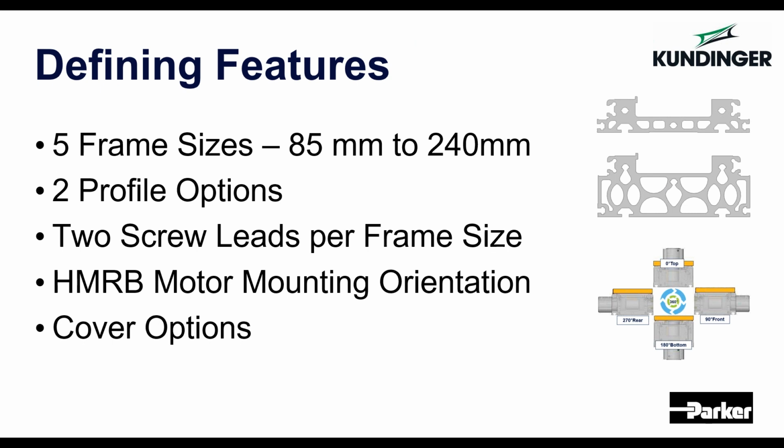So again, it can be ordered with or without strip seals, and strip seals are an industry standard sealing element, but they are wear items, right? There's end caps, wipers, and seals that will wear out over time and would periodically need to be replaced over the years. So if you don't need IP54 protection, I would definitely recommend going without it. You're minimizing your product life cycle cost, basically.